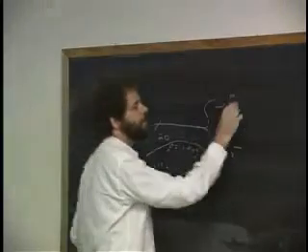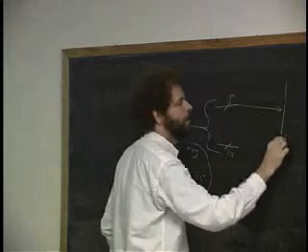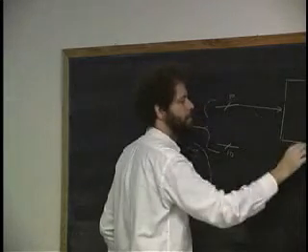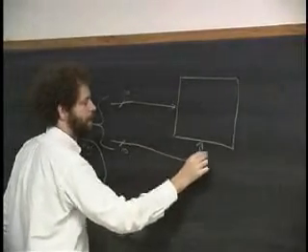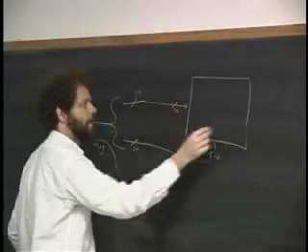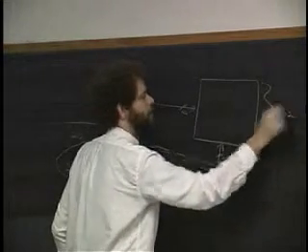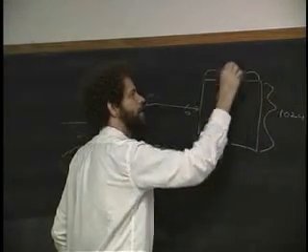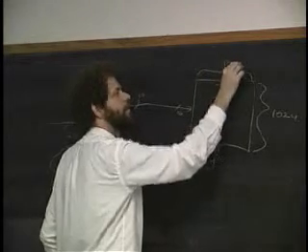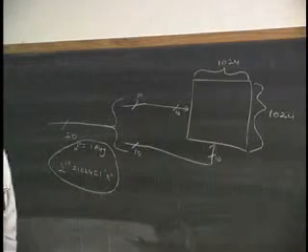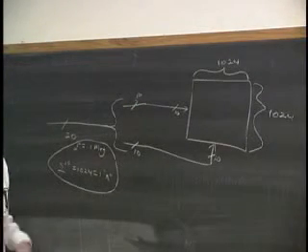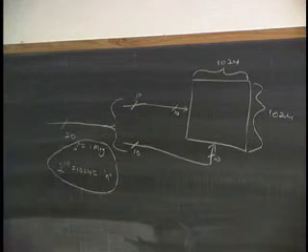And so this will then go to a structure which is square, and we'll have 10 bits here, 10 bits here, so we'll have 1,024 rows and 1,024 columns. And that's reasonable to build. Okay? So, that's how we're going to build big, slow RAMs.